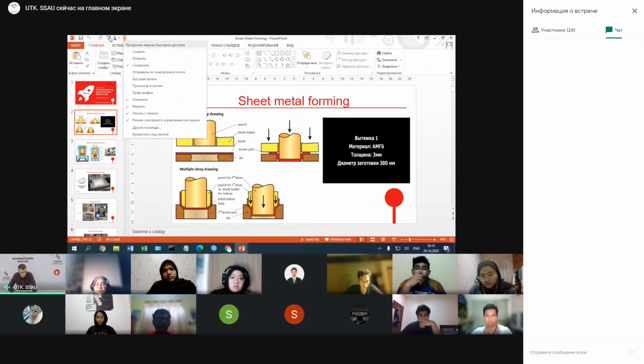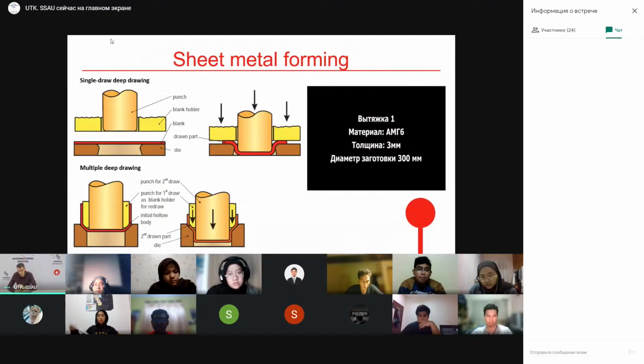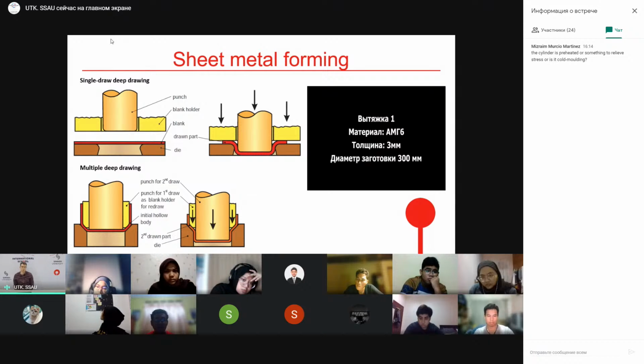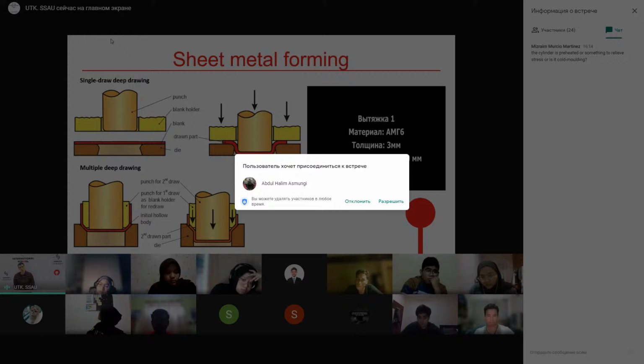What is the main disadvantage of such process? The main disadvantage is that we need a big amount of tooling. So we need at least punch, die, and blank holder, 3 parts. And if we are speaking about mass production, for example, the automotive industry, where we need to obtain a big number of parts, the cost of such production will not be very high, because the cost of tooling will be divided by the number of the parts. For example, if we are speaking about thousands of parts or millions, billions of parts, the cost of tooling is not very important. But if we are speaking about...